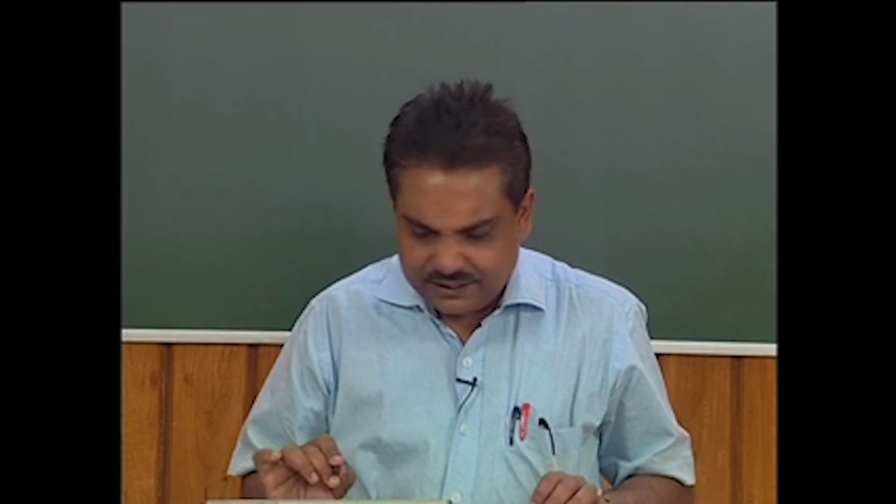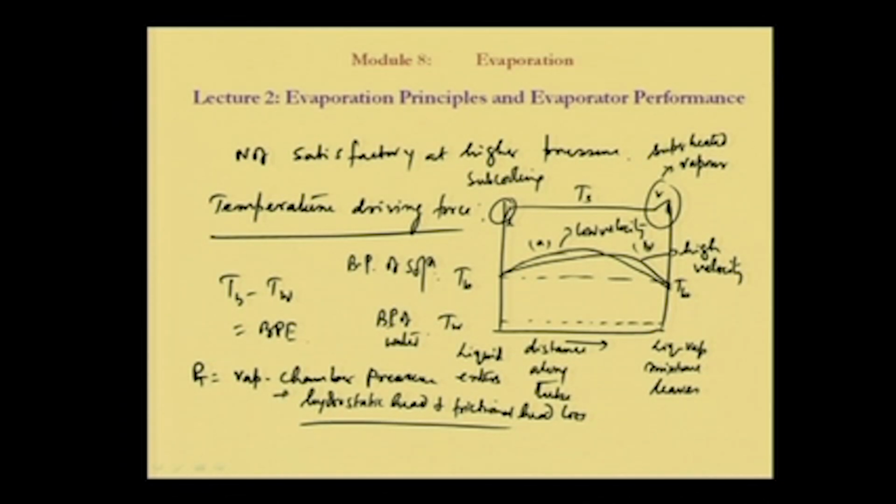Now, this is what is called the true boiling temperature. So, the true temperature difference is a variable one. This is the temperature of the liquid inside the tube, and this is the temperature of the steam jacket outside the tube. So, Ts minus this temperature should be the true or actual temperature difference in case of any flow, but what is being taken is the boiling temperature under total conditions, as the temperature difference on an average.